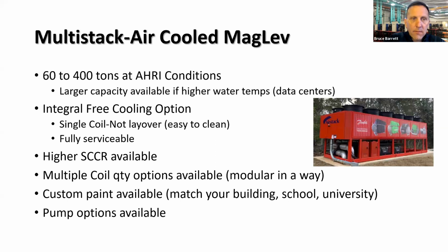Again, just to reiterate, our integral free cool option is not layover coils. It's fully serviceable, fully isolationable on the water side and the refrigerant side. Higher short circuit ratings are available all the way up to 100K short circuit rating. Different coil options with coatings if you've got a coastal environment. Custom paint, as it shows in the pretty red picture there. And pump options on board are available.